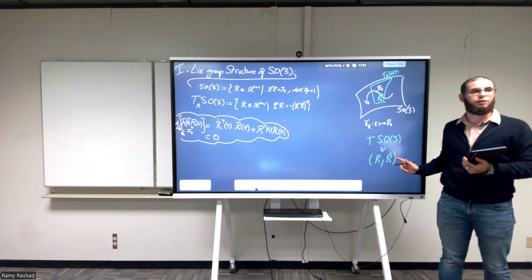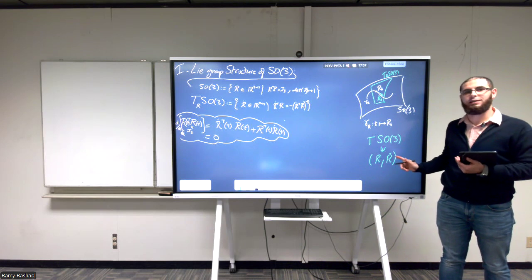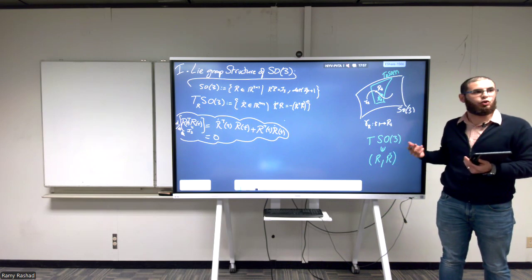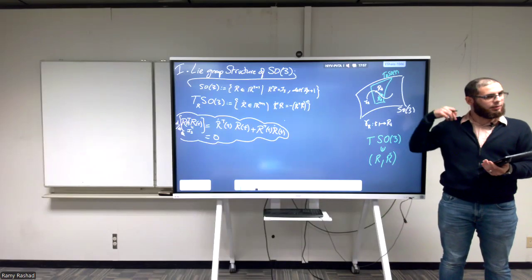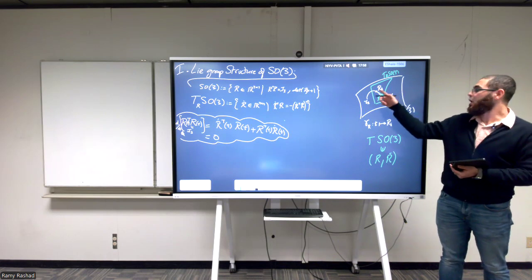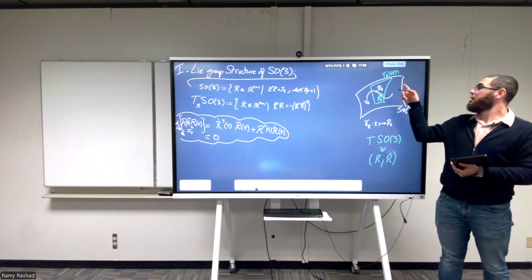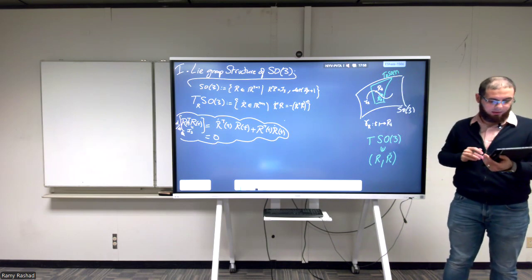So this is the rate of change of an orientation. If I cannot tell you what the rate of change of the orientation is, you cannot use this information unless you know what R is at this instant in time. So they are coupled together. The picture here is that R dot is a tangent space to SO3 at that point R. That's why they are coupled together in this way.